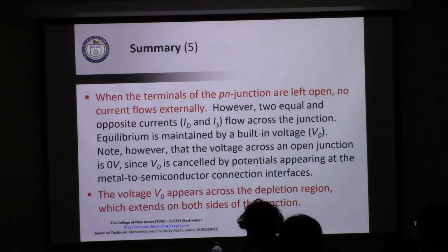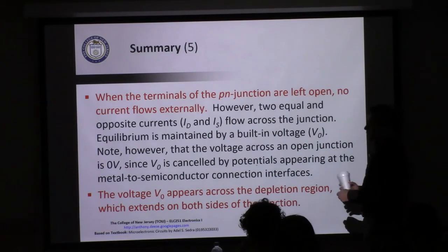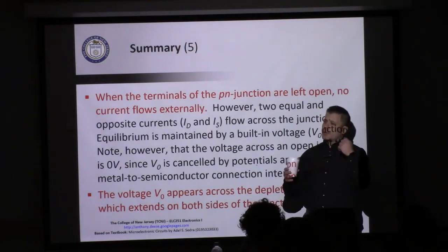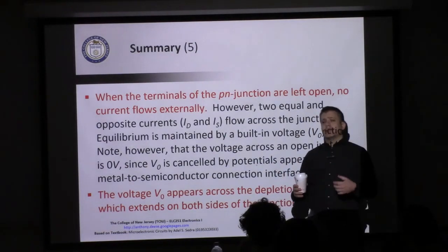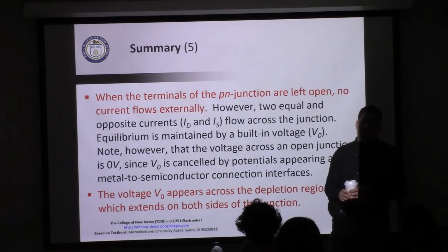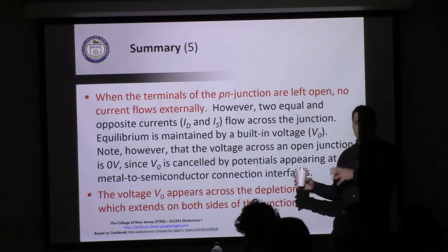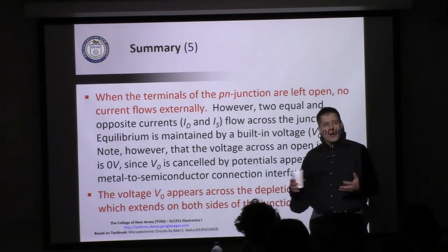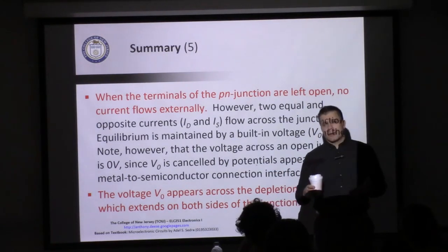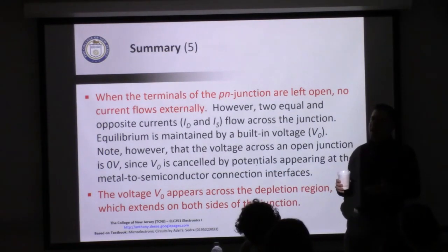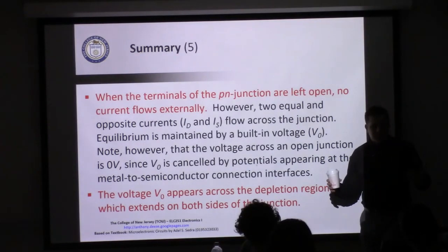And then we moved into the structure of a pn-junction, which is essentially your p-type doped semiconductor put together with your n-type doped semiconductor and some terminals. We started out discussing how it works when it's open circuited, or when no external components are connected to its leads, and this involves the formation of the depletion region.